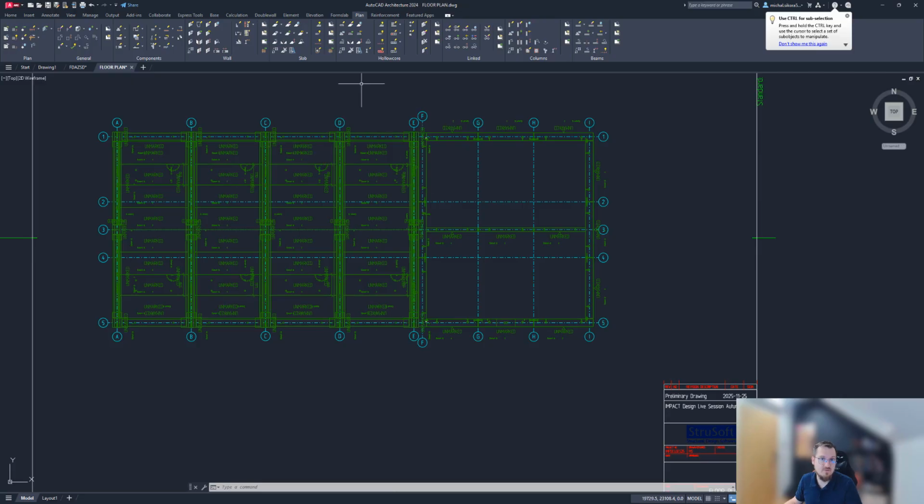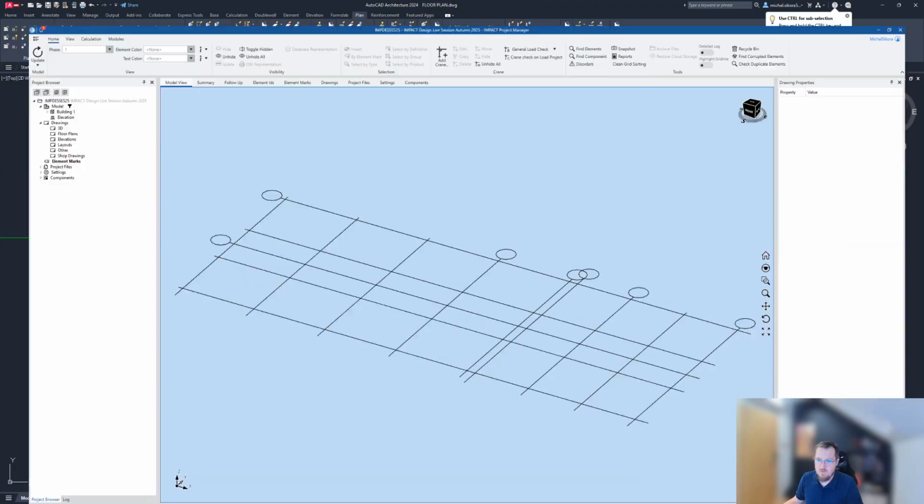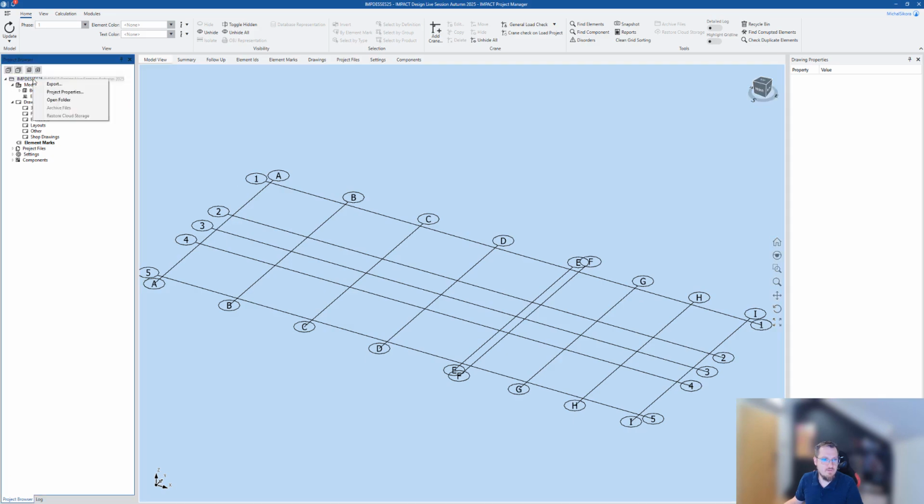But before we do that, I need to actually start saving the elements to the database. So I'll save all the walls that we have. So our sandwich panels, and let's go with SW1 as a start number. We're just going to save those. This is going to take a short while to do that. In the meanwhile, while this is saving and while the other elements will be saving, once I save those, let's go hollow core, all hollow core. Let's save that.